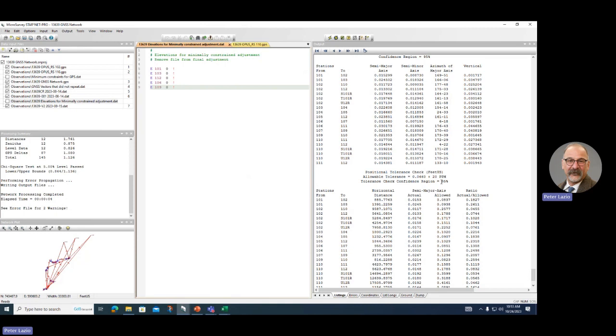And we had to put less weight on our traverse, which, we're running a traverse with a 2-man gun with what I feel is our best field crew at running traverses. Stephen Down can turn a set of angles with that 2-man gun. And I was literally throwing out some angles that they had because it wouldn't pass that. That's the worst kind of data manipulation.